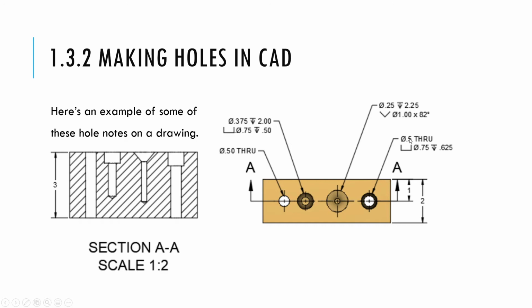This guy here, that's a 1/2 inch through. So this is a 1/2 inch through, that's that middle part right there. Then it's got a counterbore feature put on that's 3/4 of an inch that goes down, it looks like, 5/8 of an inch. So this guy right here, around the outside, it's got a ledge around the outside like that. You'll notice they also dimensioned this thing as 2 inches wide, and the centers of all the holes are 1 inch away from this back wall here.